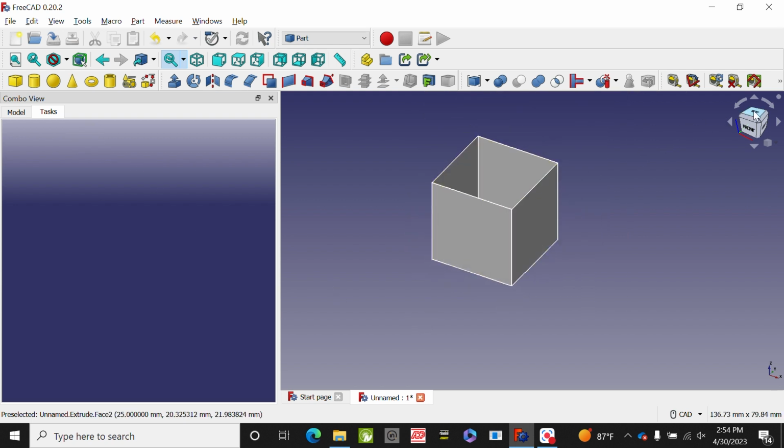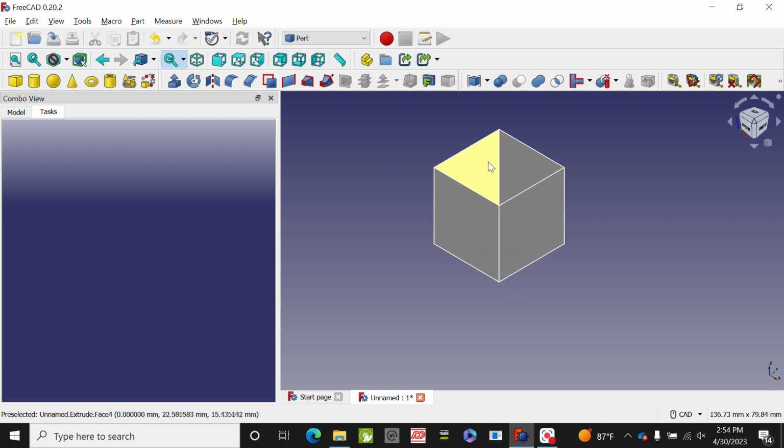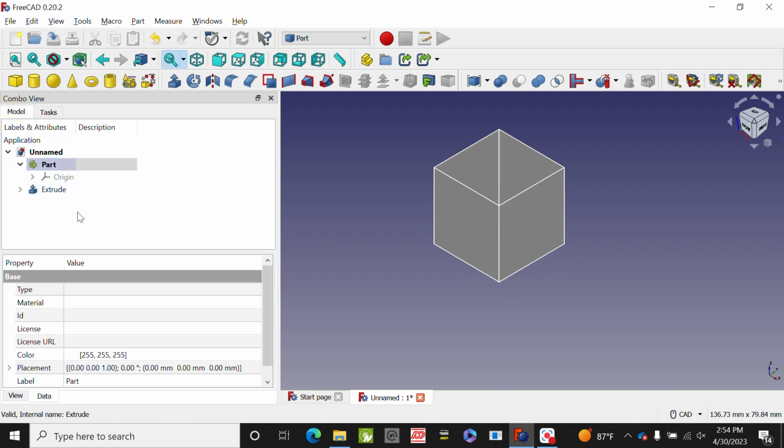This part right here is not a solid, it's a set of surfaces. Why? Because I'm extruding a line up. So what happens is that those lines are gaining material on the Z direction, which is up, but it's not a solid. So if this is what I want, excellent, it's perfect because I can do a door here, an extrusion to cut through my booleans.